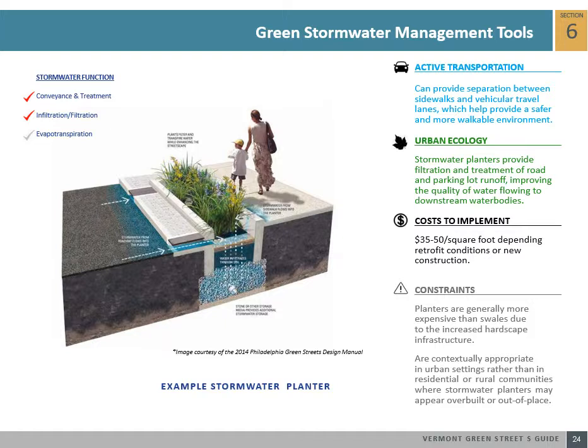When there is interest in preserving existing trees in urban areas, suspended pavement, structural cells, and engineered soils can be used to create a bridge between a vegetated strip along the road and a green space. The bridge entails removing paving and compacted subbases in between the tree pit and the green space, and replacing the subbase with structural soil, and then repaving.